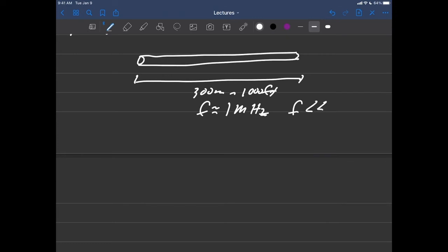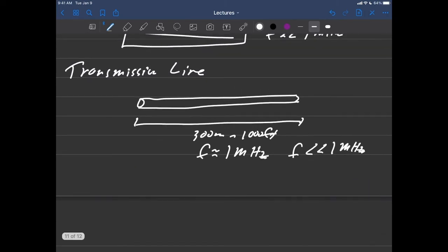I really should choose any driving frequency to not just be less than 1 megahertz, but maybe much, much less than 1 megahertz. Because what I do not want to happen, say with a sine wave that I might have injected into my transmission line, which we did in this lab, is I don't want these harmonics to start happening. I don't want these resonances to start happening. I don't want the transmission line to start sustaining resonance modes like that, because that's where the unpredictability of the circuit might come from. And I think we hit that at least a few times.